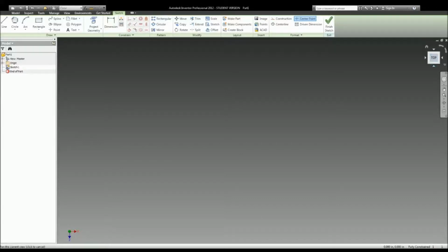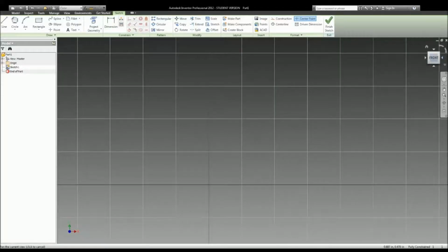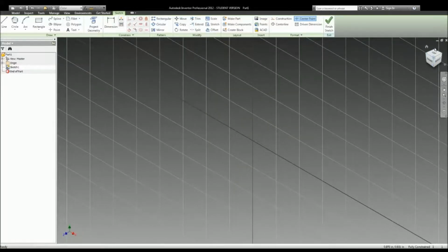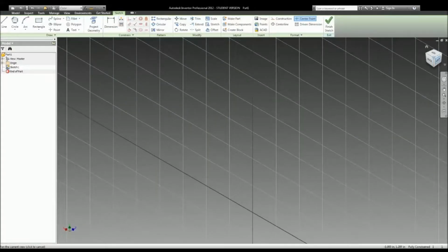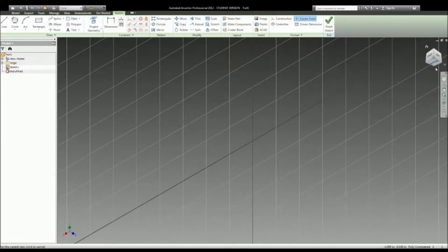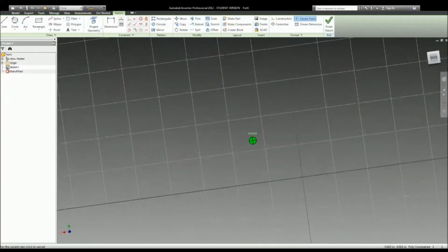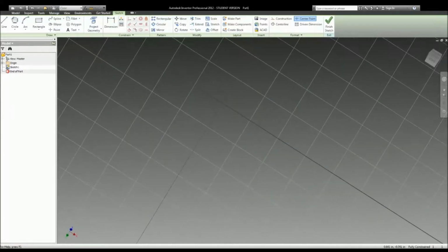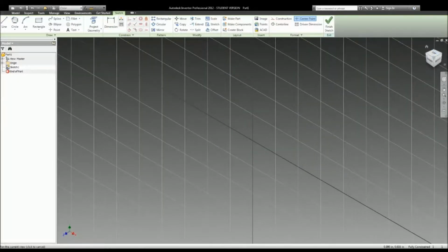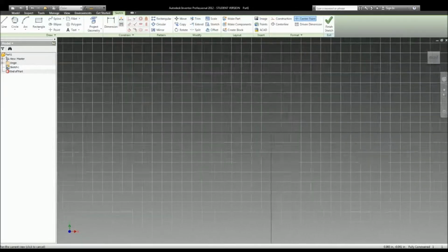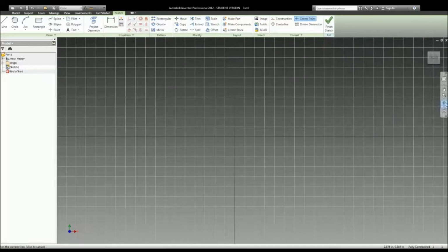This box can go to any of the other faces that you want. So I'm back to the front, go to the right. I can go to the top right. I can go to the back, top right. I can go to the bottom. And you can also click and drag so that you move the shape around at very weird angles. Or if it gets to a point where you can't navigate back to where you need, you can just click this home button and it'll take you to this isometric view of your object, and you can reorient yourself from there.